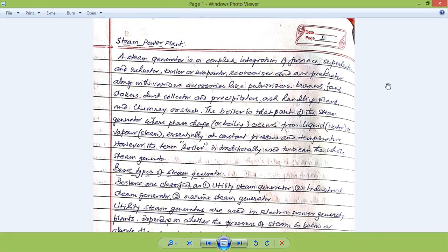There are various other equipment like pulverizers. What is that? You receive coal in different sizes of particles, extracted from different mines, but those particles cannot be used directly because the furnace requires a specific size of coal input. So you have to pulverize or break it into a particular size, as I discussed earlier, and that operation is done in the pulverizer itself. Next, the burners.